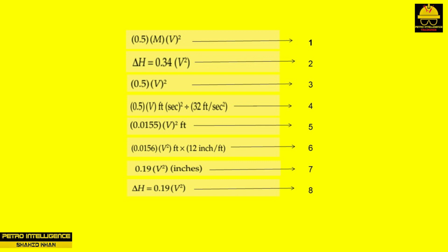The actual theoretical calculation for converting head to acceleration. Step 1, let's assume that I have 1 pound of liquid flowing through a nozzle at a velocity of V feet per second. Step 2, to increase the kinetic energy of the liquid from no velocity to V requires 0.5 m V squared, or since m equals 1 pound of mass we can say 0.5 V squared.